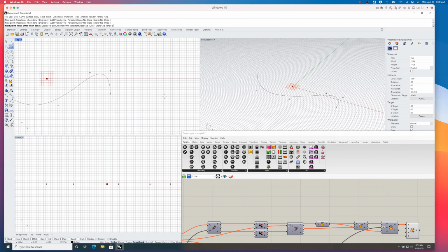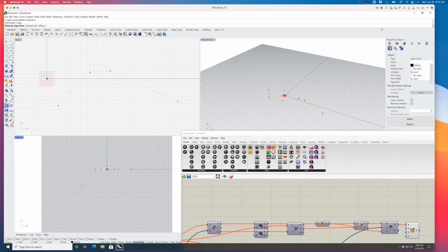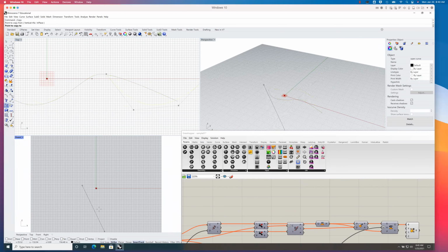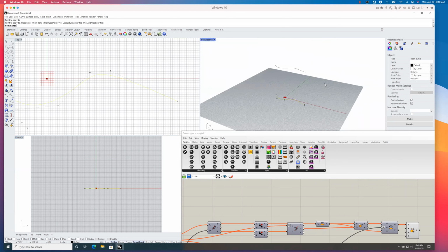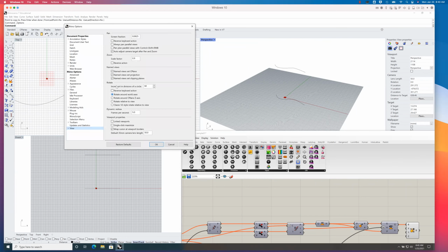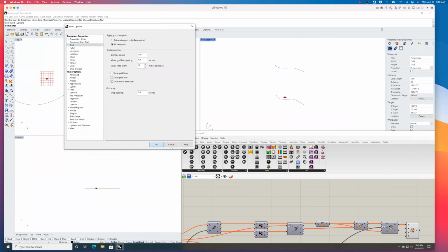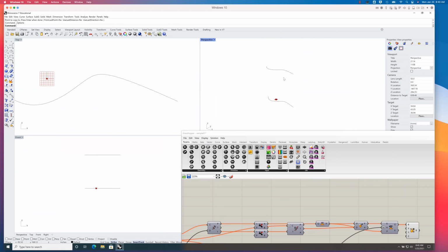But I'm just going to make something obviously not planar. So I'll draw a curve here in space. If you can see my screen in Rhino. I'm just going to zoom out a bit here. In side view, I'll go ahead and constrain to ortho, and I'll make a copy of this up here. Okay. And here, lastly, I'm just going to turn the grid off. This grid is really overly dense. It's kind of hard to see around it. I'm just going to turn my axes and grid off.